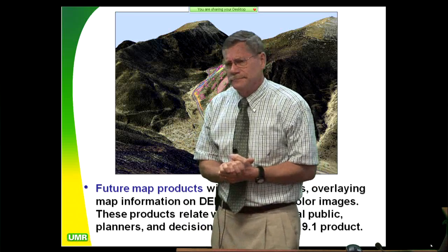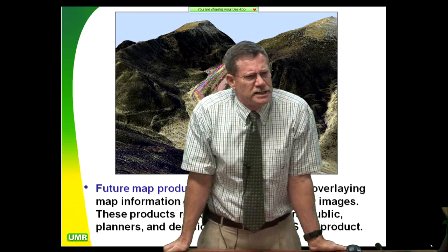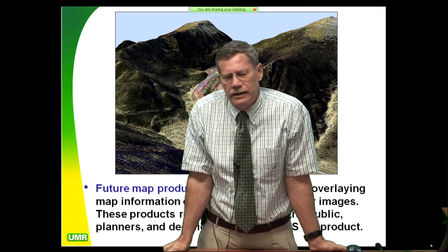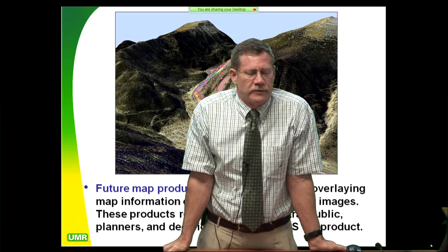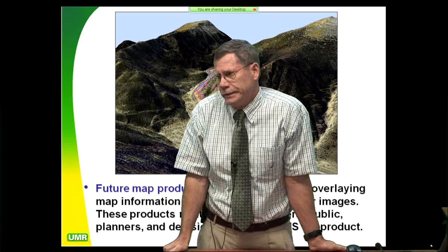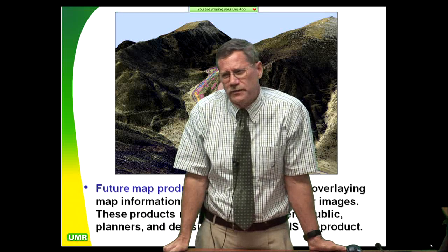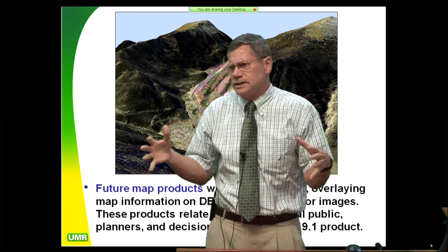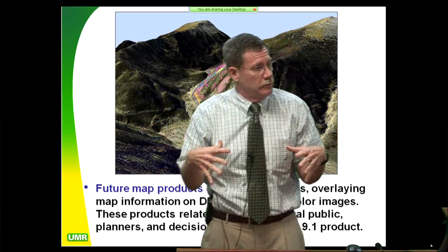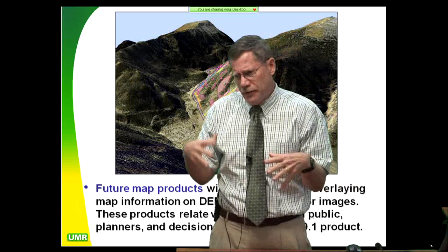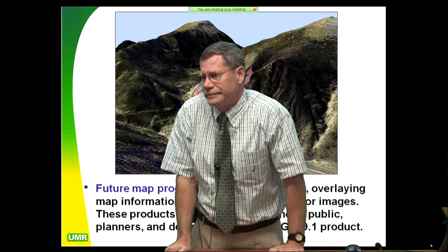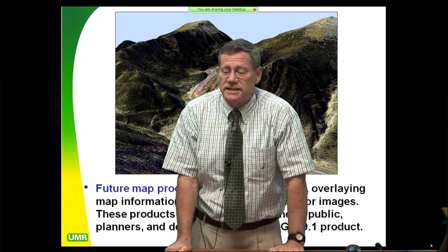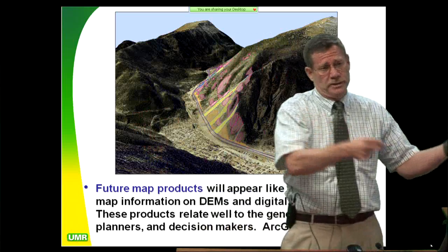Anyway, here's what happened in California. That storm on January 1st, 1997 was 6 degrees warmer than any previous storm that had hit California on New Year's Day. So they got a tremendous amount of coincident melting. They had a storm that came in and dumped upwards of 30 inches of rain over a 3-day period, and they had about 18 inches of coincident melting. So they had a net runoff event of 50 inches, and their models were maxed out for 35. So they overwhelmed their flood storage.